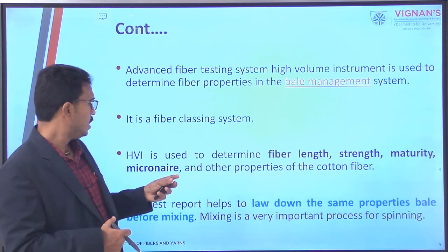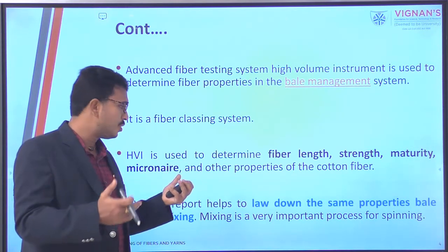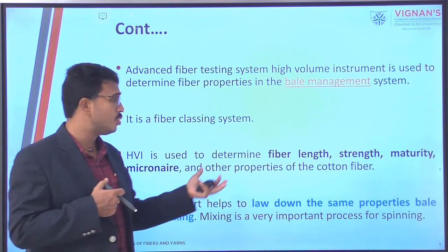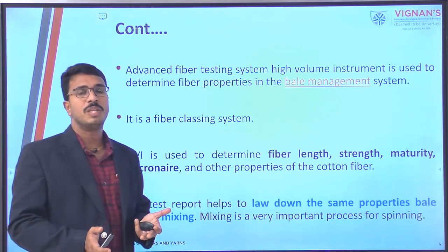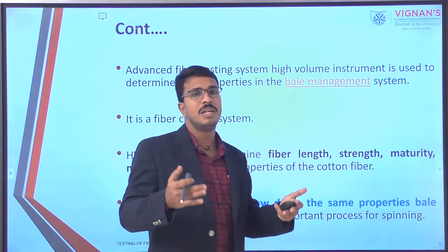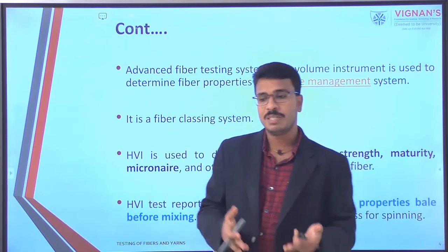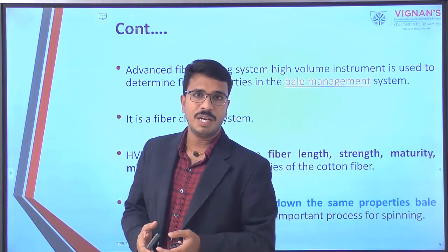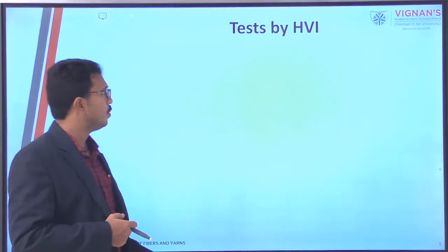So the HVI, high value instrument test reports help to lay down the same properties of the bale before the mixing. If the bales have the same or nearly the same properties of fibers, obviously we will get good quality of yarn, and that can be done by using this HVI test report.